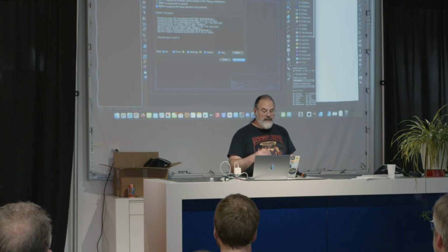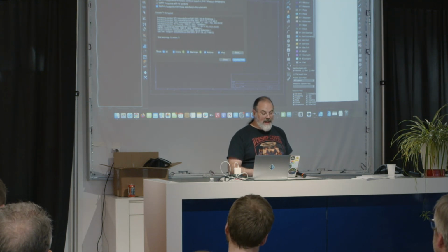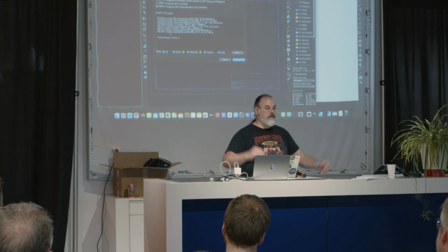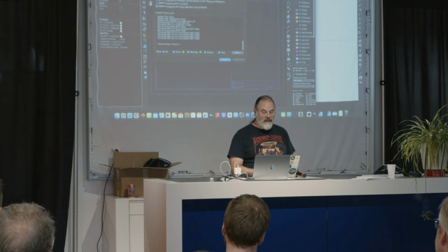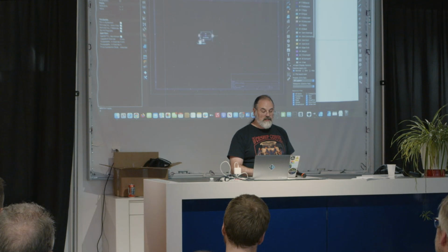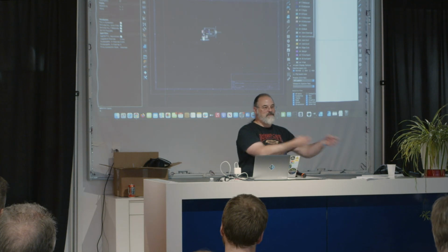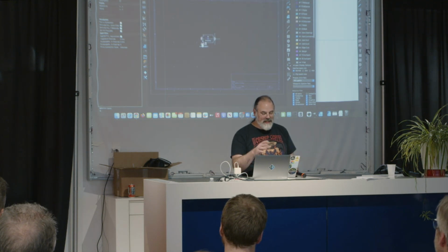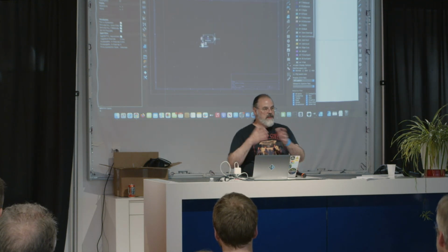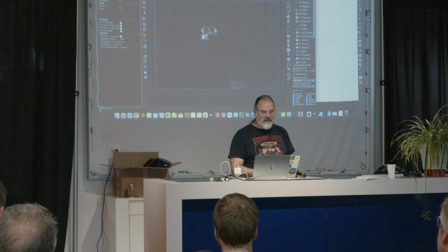Once I hit update, it looks like this is going to add a couple of components, obviously the missing components that I don't have on my PCB yet. And you can see it's already stuck to my cursor, so I can place it. It's not dumping it off in the corner out of your board somewhere, where you've got to go get those back in somehow. So it's kind of nice. If you're doing incremental changes, it makes it a lot easier to get this thing going. I'm just going to plop those down right there.